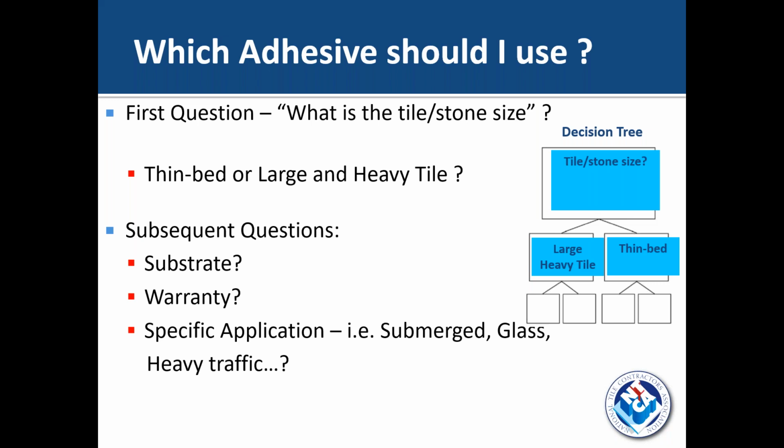All right, so here's Richard Bowman again. We require movement joints, but do the adhesives enable sufficient movement to occur for the joints to close without shear occurring? So if you're closing the joints with thin set or grout all the way to the walls, I can guarantee you don't have any movement joint in there. You have no room for sufficient movement.